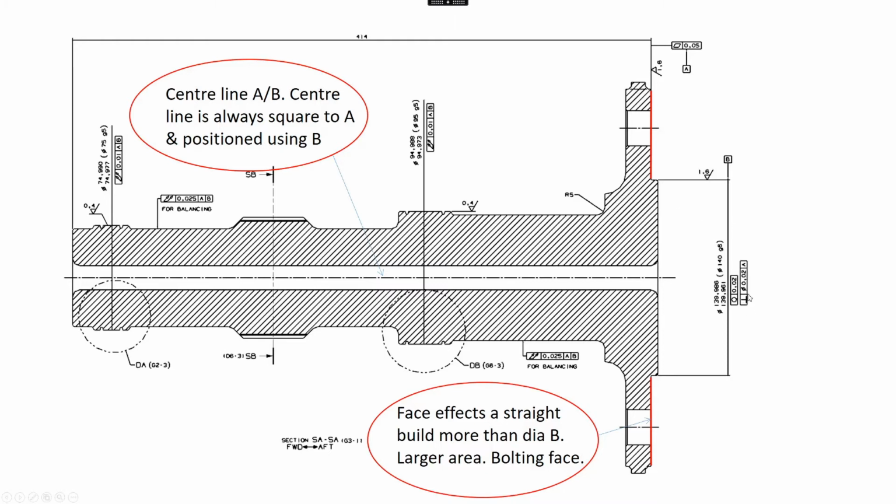So we've got the squareness value here, we've got a diameter 0.02 to A. So we're making sure that this is square to this. And this is sort of some things that people miss when they first do detailed drawings. They forget to tie in one datum to the next datum if it's important. In this case, it probably is quite important. So that seems fine. And in this case, we want to make sure that this is square all the way around the part. So in all angles, all directions, which is why we've got the diameter symbol here. So it's square in all directions.